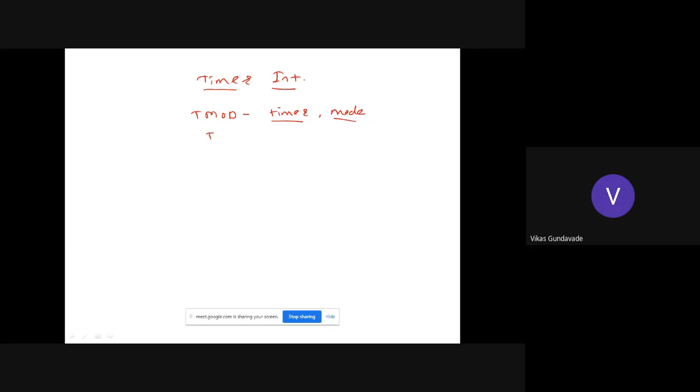After that, we use THx and TLx as a count register. Whatever count is required for the delay will be provided into THx and TLx. The next bit is the TRx bit. For timer 0 it is TR0, and for timer 1 it is TR1. This bit is set to start the timer.